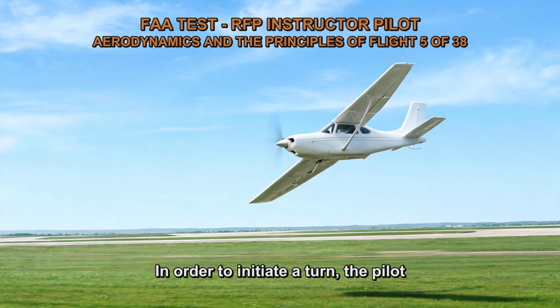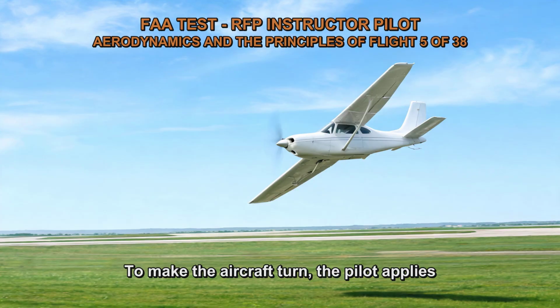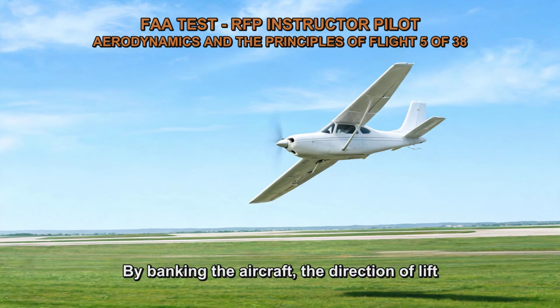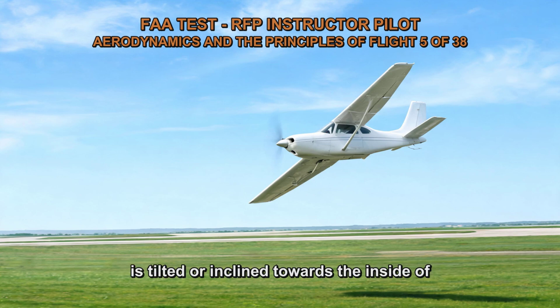In order to initiate a turn, the pilot needs to change the direction of lift. To make the aircraft turn, the pilot applies a control input, such as using the ailerons to bank the aircraft. By banking the aircraft, the direction of lift is tilted or inclined towards the inside of the turn.